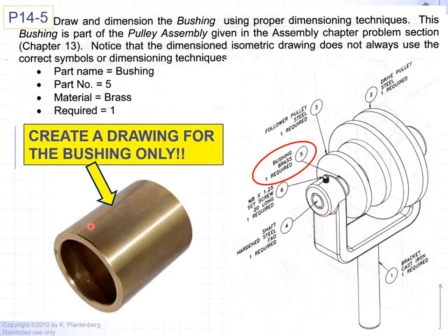So you just make this diameter slightly larger than the hole, so that you'll have an interference fit where the hole is smaller than the cylinder, or in this case, the press fit bushing. You can force it in there, tap it in there, or press fit it in there with a machine. Now in this case, they didn't put a bushing, they just put a rod inside, and we have a little set screw that holds the rod.